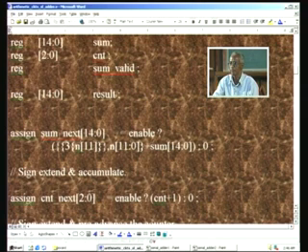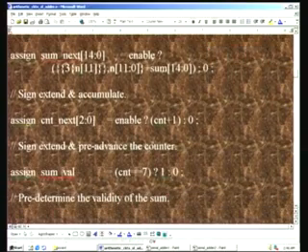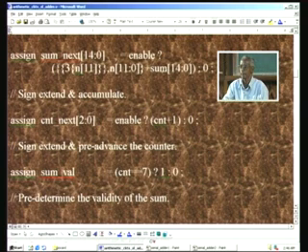So, that is what we want, and this will be registered during the always block positive edge of clock. Similarly we need to update the counter, and for that we have a count next here, and this is once again derived from the enable signal. If it is 1, then, this also being a mux realization, we increment the counter by 1 and then assign it to the count next, and this is basically a pre-advancing of the counter or pre-increment, and otherwise you initialize to 0.